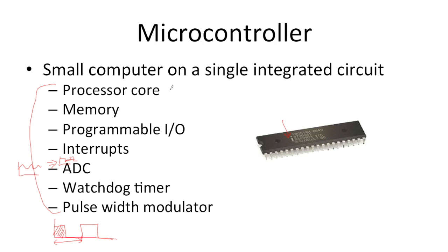A general purpose microprocessor only has the processing core, and needs to then be interfaced with various memory modules and input and output peripherals. So for a relatively small price, you can get an integrated chip with all the built-in components in it, and this chip is programmable.